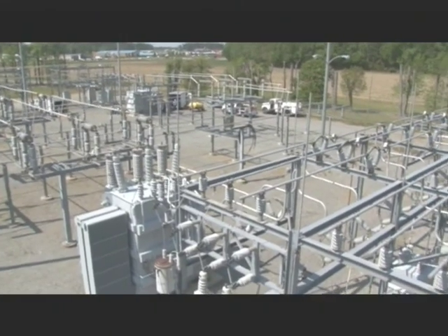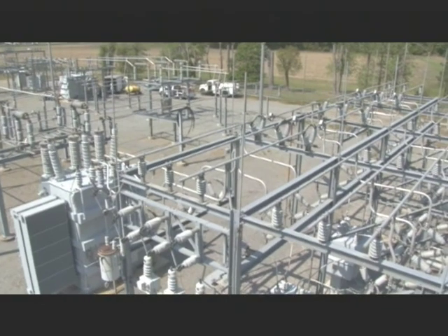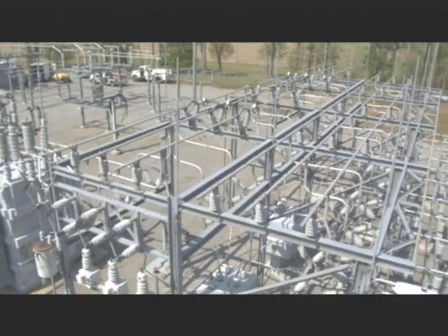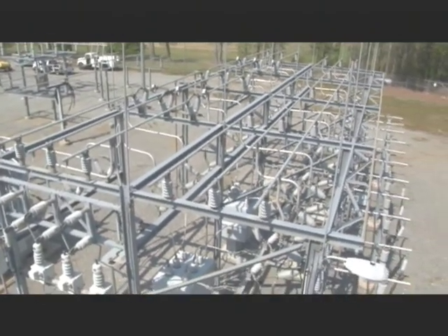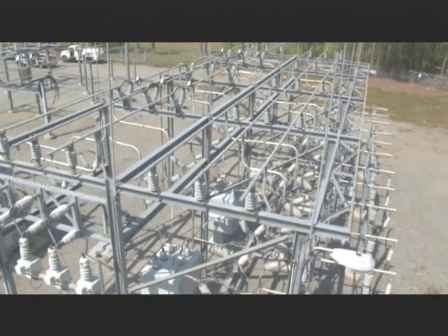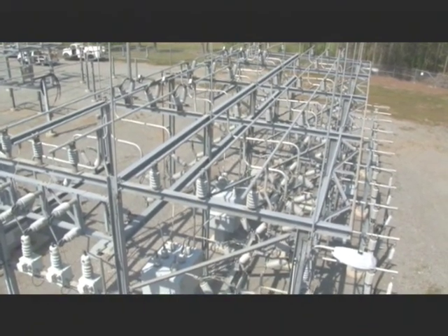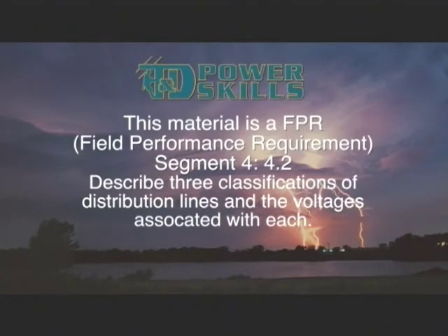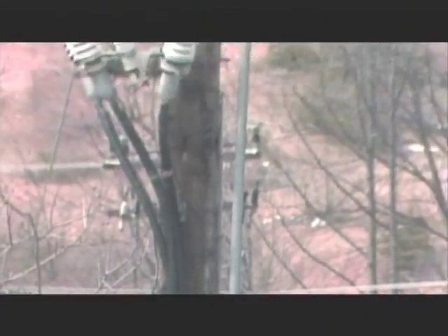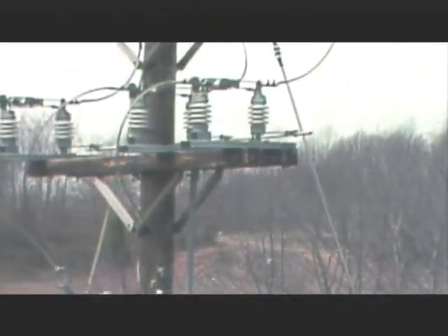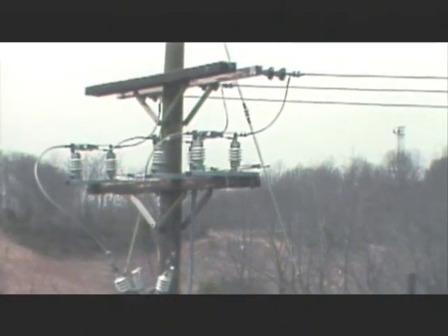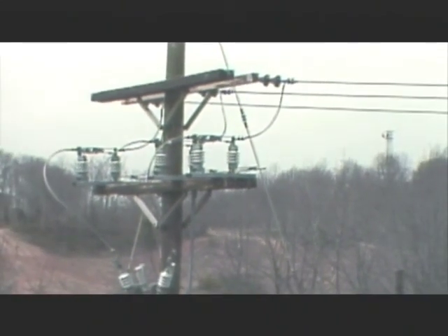The secondary side of the substation transformer is connected to a substation bus. The substation bus supplies distribution voltage to distribution feeders. A feeder is made up of a number of wires that carry electrical energy at primary distribution voltage from the substation into a service area.